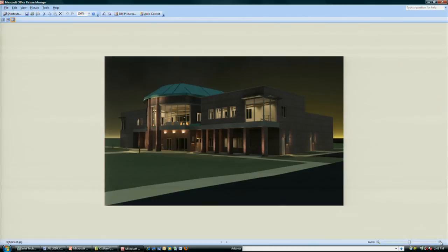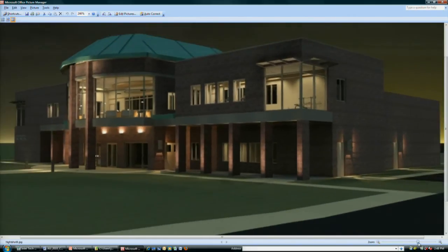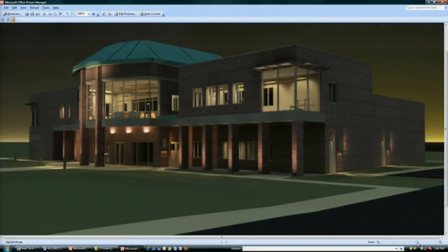So this is real-world lighting. Okay, 4 o'clock in the morning, East Coast. I'm in Virginia Beach. I had to tone down the lighting on the floor to 50%, but it is attenuating, so it's following the inverse square law for all the lighting decay and everything like that. And I had the MEP engineer put some uplighting in the front of the building for me. You can't see the fixtures because they're kind of recessed into the concrete, but they're there. I just didn't have a chance to have him fine-tune that for me, but you can see the uplighting on the columns in there.